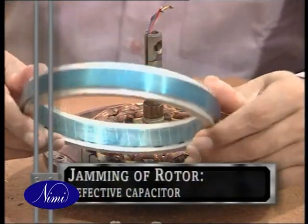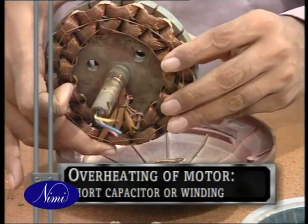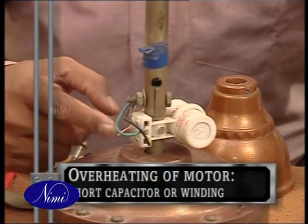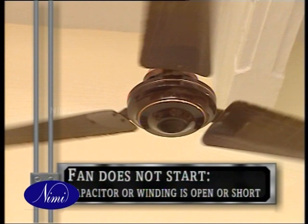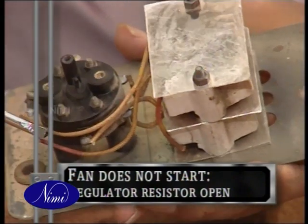Jamming of the rotor might once again be due to a defective capacitor. Overheating of the motor might be due to partial short circuit in winding. A short capacitor might also heat up the fan. A fan might not start if the voltage is low or the winding is open or the condenser is open or short. Even if the resistor in the regulator gets open, the fan will not rotate.